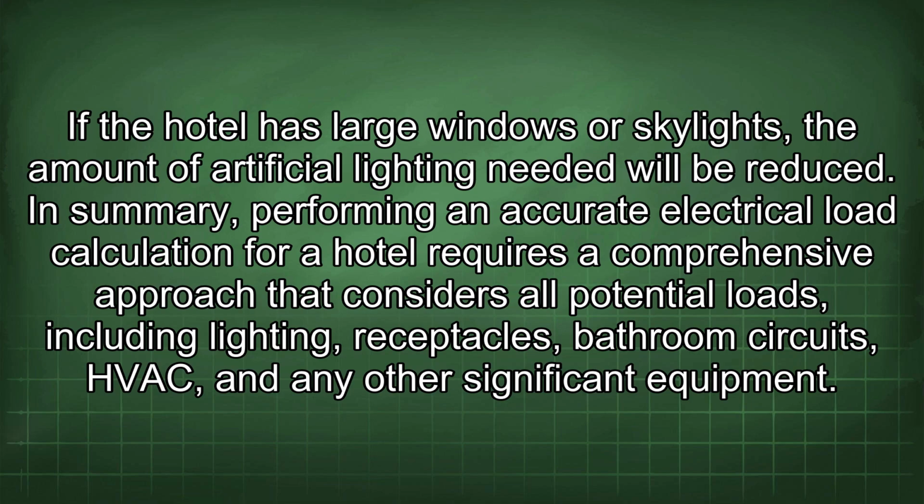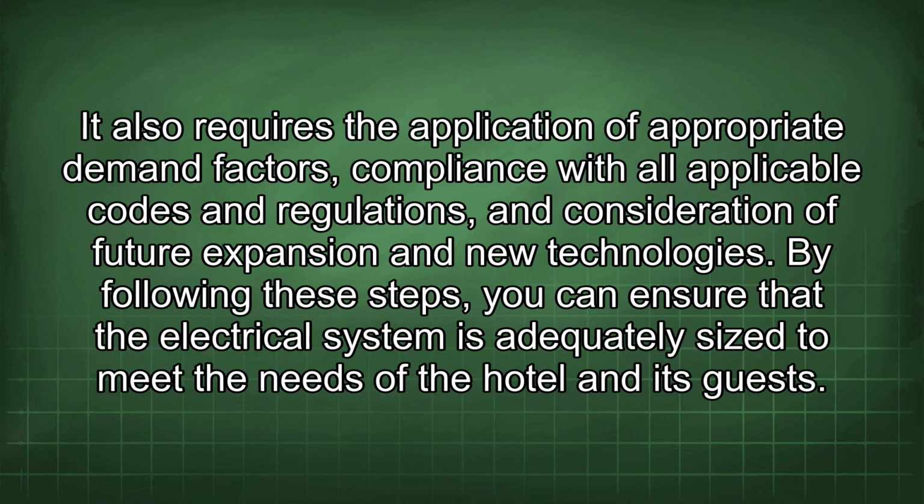In summary, performing an accurate electrical load calculation for a hotel requires a comprehensive approach that considers all potential loads, including lighting, receptacles, bathroom circuits, HVAC, and any other significant equipment. It also requires the application of appropriate demand factors, compliance with all applicable codes and regulations, and consideration of future expansion and new technologies. By following these steps, you can ensure that the electrical system is adequately sized to meet the needs of the hotel and its guests.